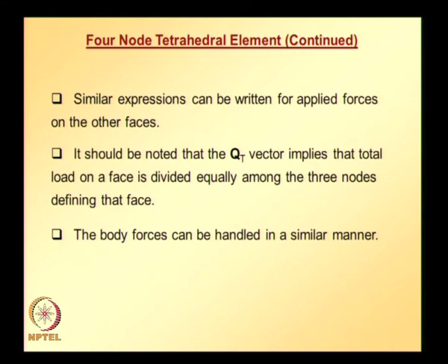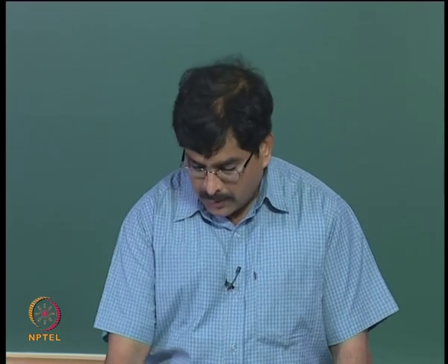Once we get the nodal displacements, we can calculate strains through strain displacement relations, and once we arrive at strains, we can calculate stresses through the stress strain relation. The stresses that we are going to obtain are going to be in terms of x, y, z coordinates, that is sigma x, sigma y, sigma z. To know whether a particular structural component or mechanical component satisfies certain failure criteria or not, we need to know what are called principal stresses, which are different from sigma x, sigma y, sigma z, and all these shear components, that is tau xy, tau yz, tau zx. So, now let us look at how to calculate these principal stresses.